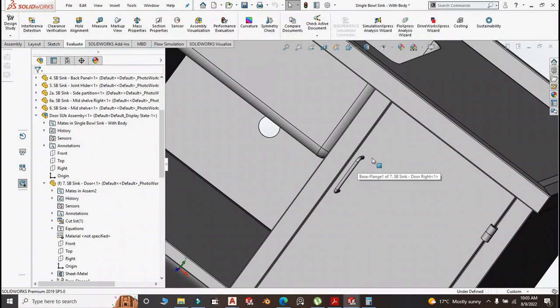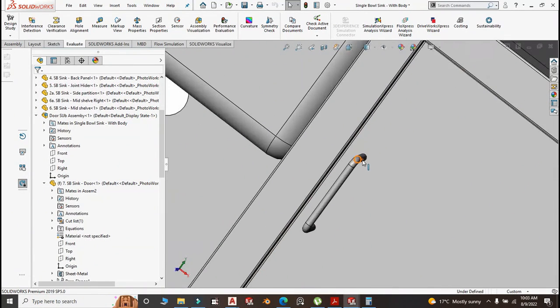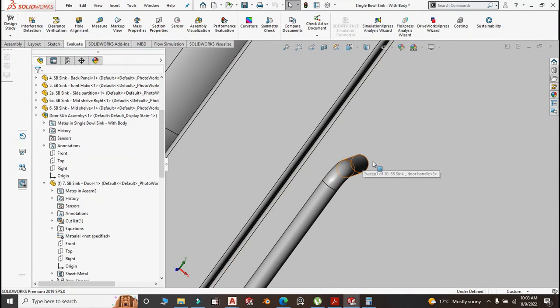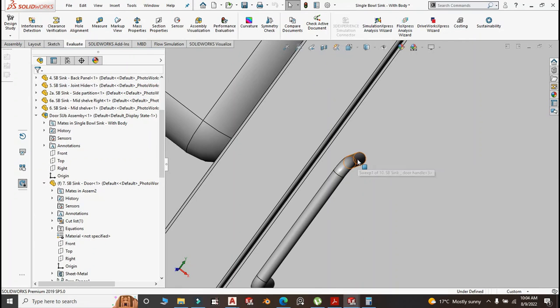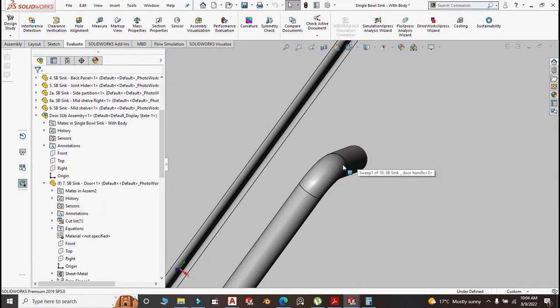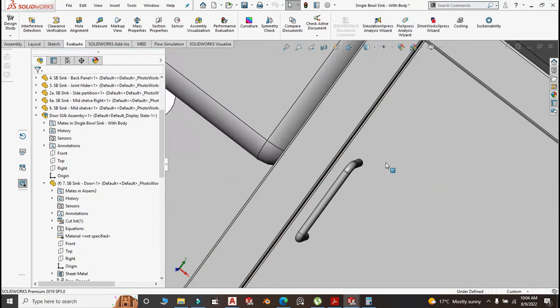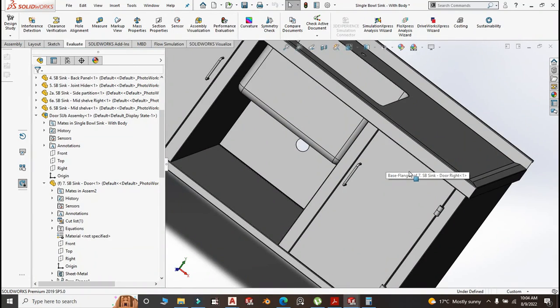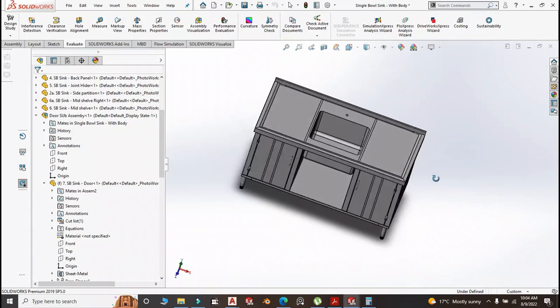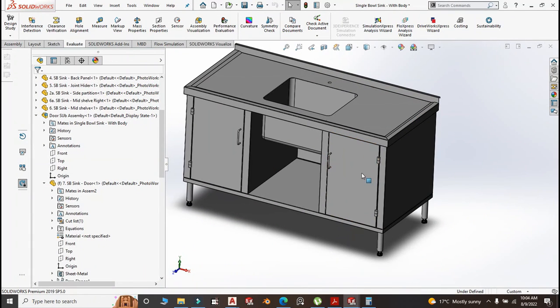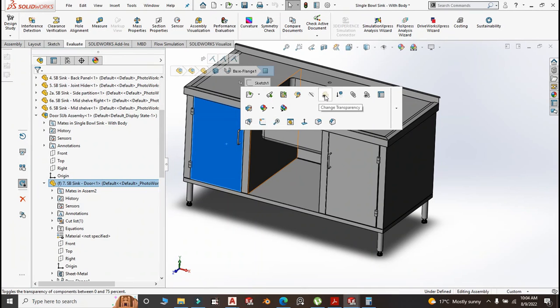I strongly advise, don't weld here. Some people can take this handle and do welding. It will look ugly. Just do some nice tap thread there, then your screw. Do it from the inside. Anything else to be mentioned from here? No.